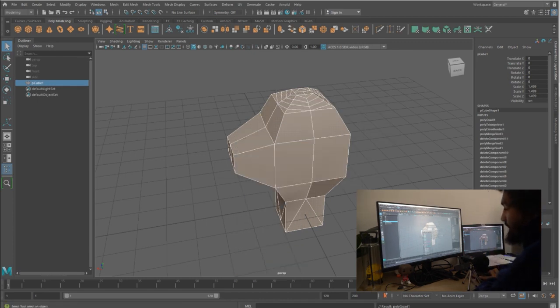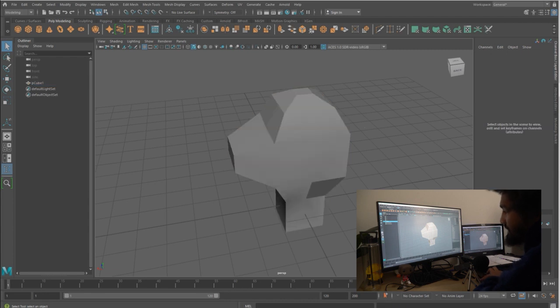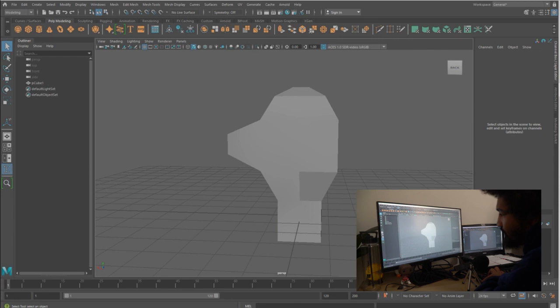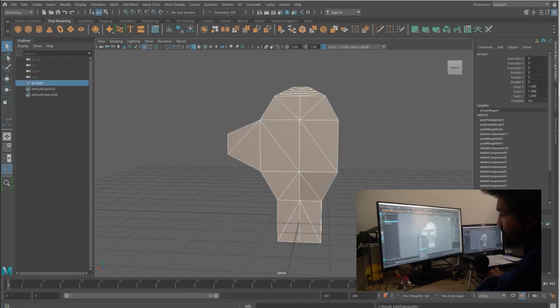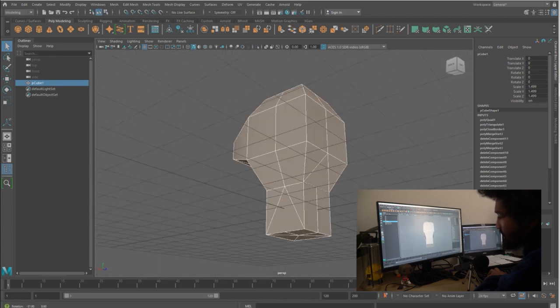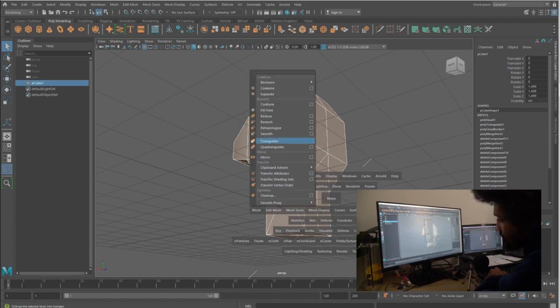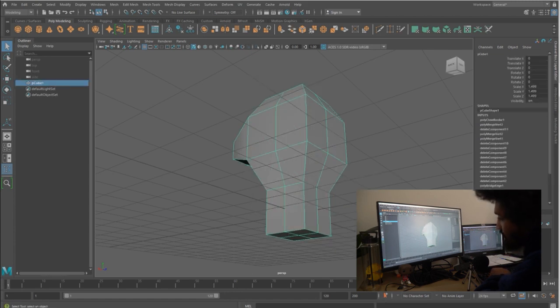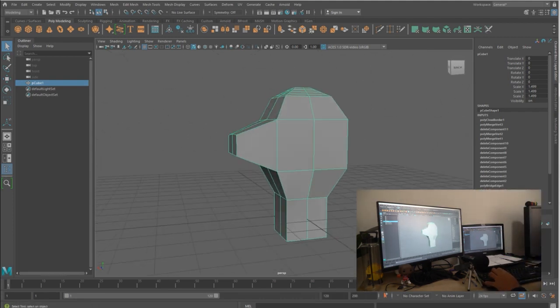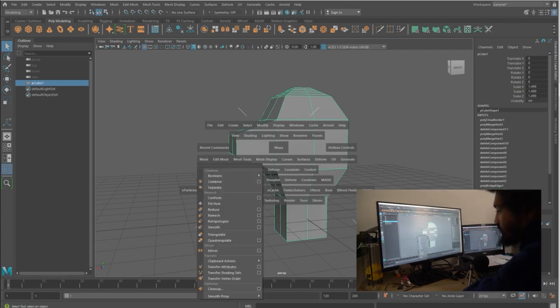Here you can do it easily because it was just split in the middle, but still there is some part here it can't move, so it's not that smart. From mesh to triangulate, it's gonna create those two edges, but going back it's gonna remove them, so we have these kind of weird triangles now that we can just remove. You see here too there are some artifacts. This is some very wrong automation. We really want to make sure we do it manually, so we're gonna Control Z to come back to our geometry. Whatever geometry you have, even if you don't have this one, it's just for you to test the tools and understand what's happening in the software.